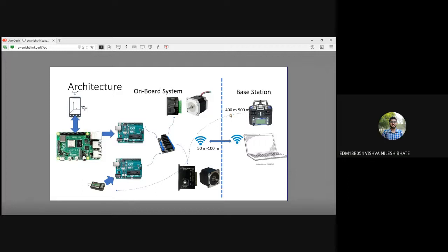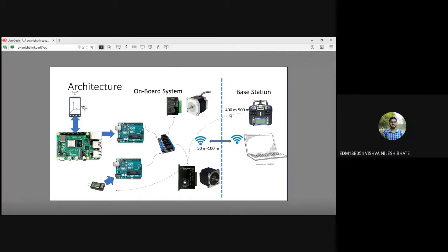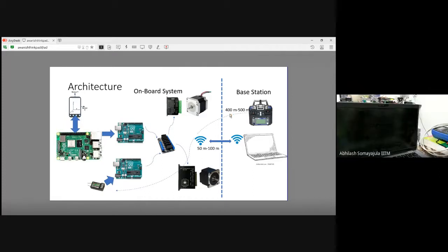We can pass it to the other Arduino and say, okay, now you stop, you don't have to process any further data. So I think it can be done, but I think it's better not to do it, because that kind of makes your redundancy go away. You don't want this Arduino to be communicating with the other Arduino at any point of time, or even if it communicates, you don't want to rely on that connection. That's the whole point of the redundancy, isn't it?